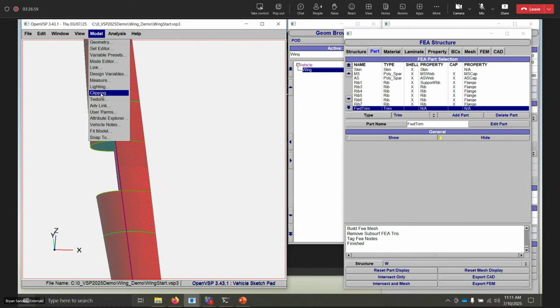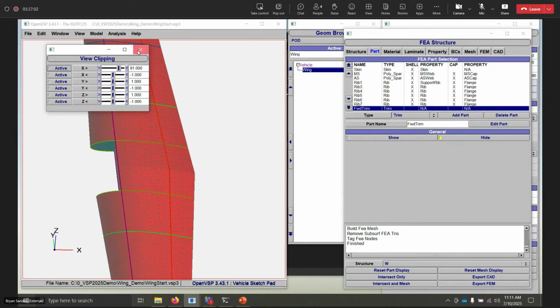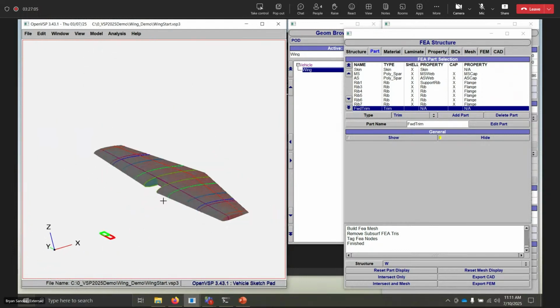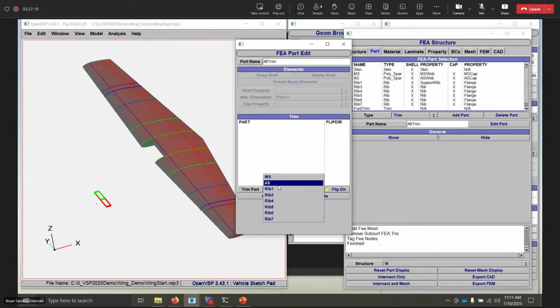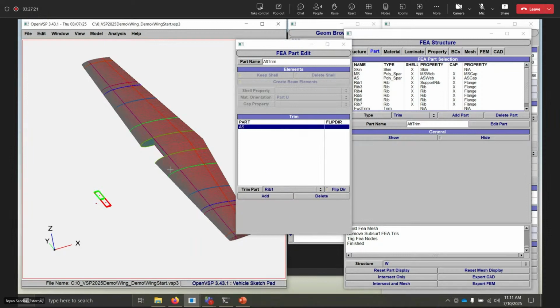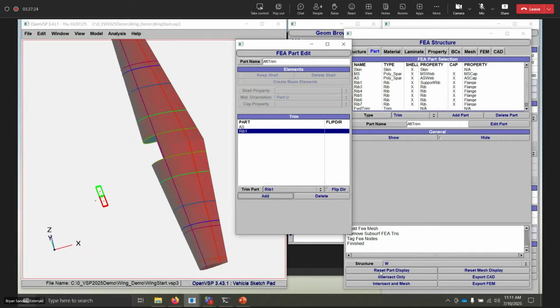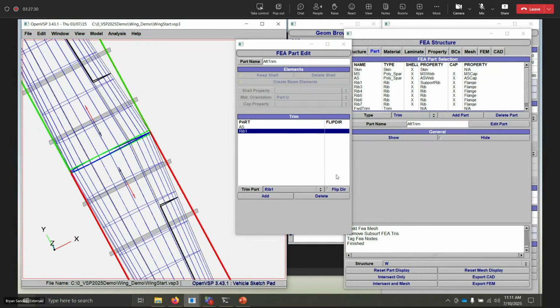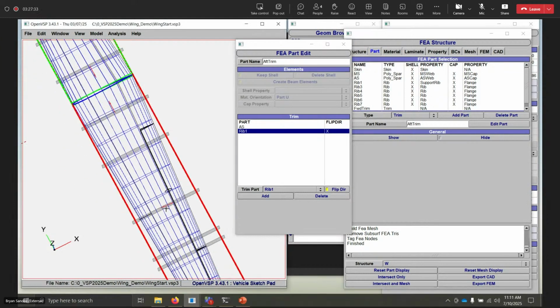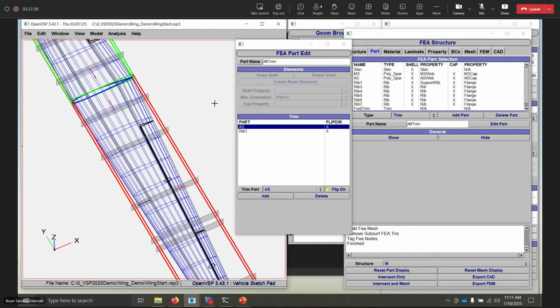I always forget turning off clipping, particularly with this inch foot thing or millimeters and meters thing. That's another way to hide yourself from your part if you forget to turn off clipping. So we'll add another trim. We'll call this aft trim. We'll add the aft rib and that rib 1. And this rib 1 we need to change, but the aft one is pointed the wrong way too, so we need to change it. So now we're going to trim out that back part there.